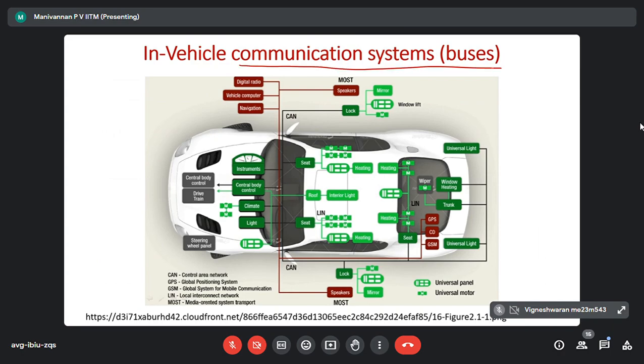Okay, sharing data between different ECUs inside the vehicle is done using wired communication. The CAN bus, the MOST bus and LIN bus all use wires. Without wires, they don't work. They send electrical signals only in wires, like a binary signal, zeros and ones, 0 volts, 5 volts, like that, or 2.5 volts to 3.5 volts and 1.75 volts.